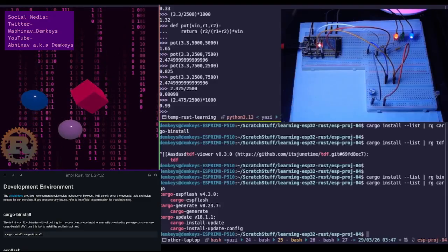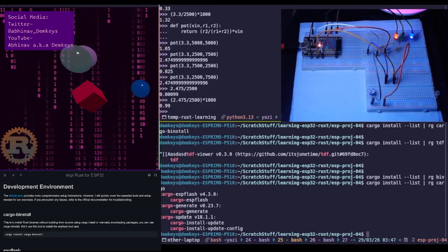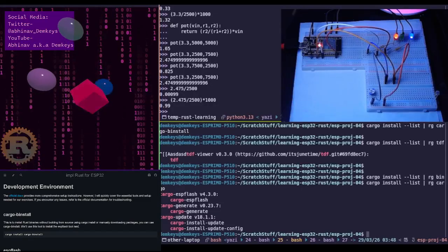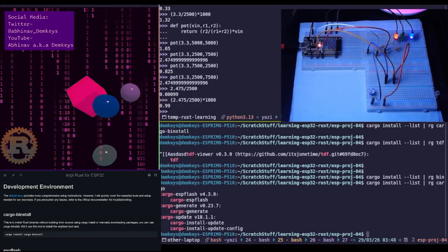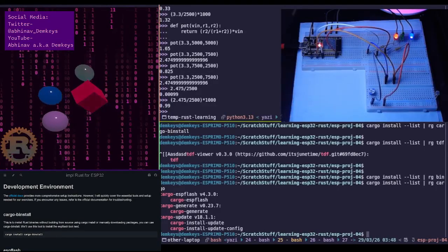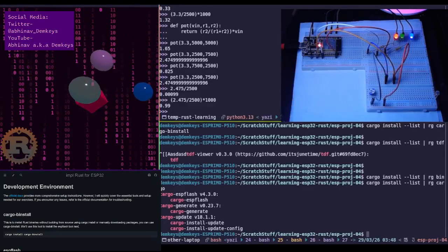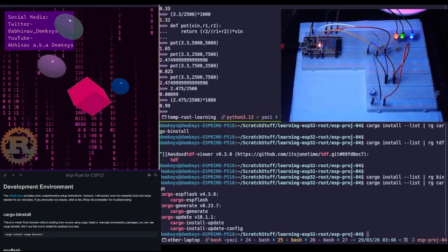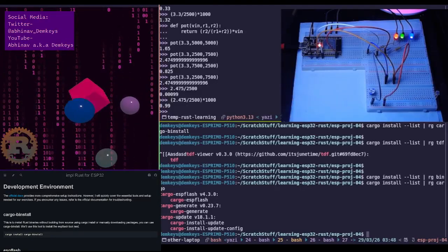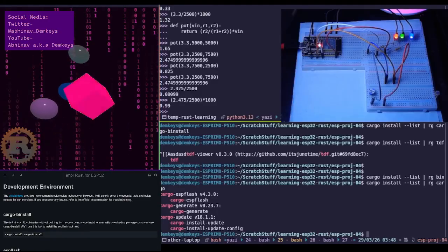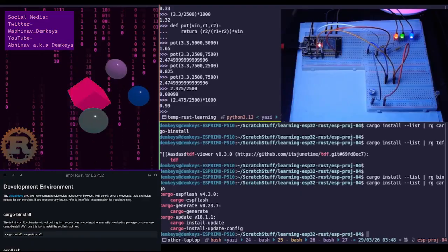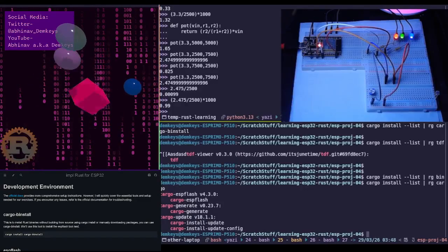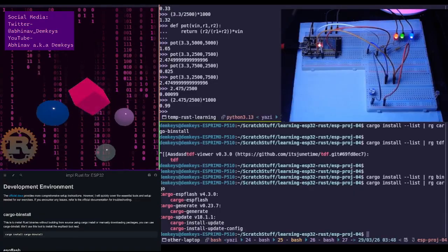The relay itself has specs, and the trigger, essentially, you can specify, or you can buy relays that have their trigger to be 5 volts or 3 volts. So if you're working with an ESP32 that usually deals with the 3.3 volt range, you want to go for the 3 volt thing. If you're working with an Arduino, then you want to go with the 5 volt thing. Otherwise, you're going to have to use a level shifter, and things get a tiny bit complicated there, but it should still be possible.